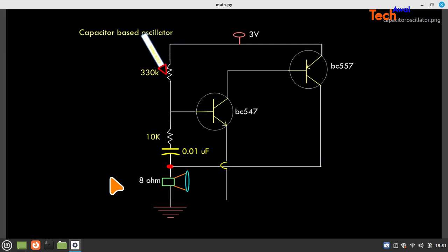Okay, now if I connect this circuit, if I think that there is a switch and I connect this circuit, so as per the characteristics of the capacitor, a charge would start accumulating in the capacitor. Okay, so at the beginning when the capacitor is discharged, this would behave as a short circuit.